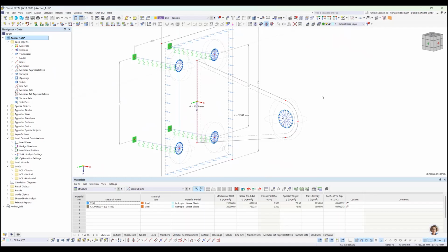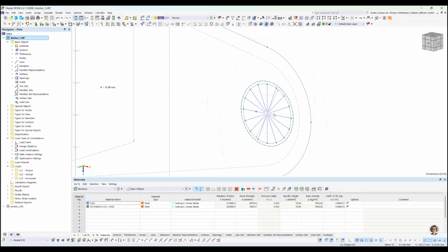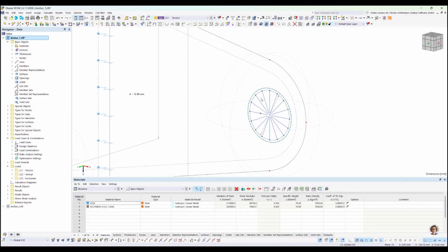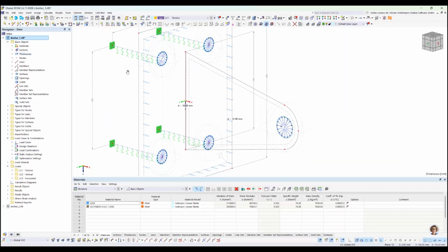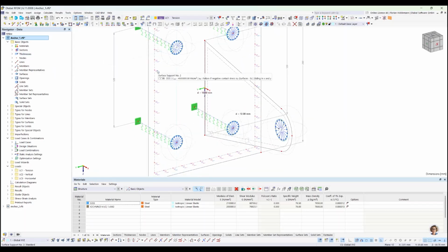I would like to show you the basic initialization, the setup for the add-on optimization, and how it works together with the stress-strain analysis. We do some design setup here as well. And I would like to point out some nice details in this model. For example, how to properly model screw connections, or to get a more realistic result when applying the loads on holes like this, and have a backend plate with a non-linear support for the surface.